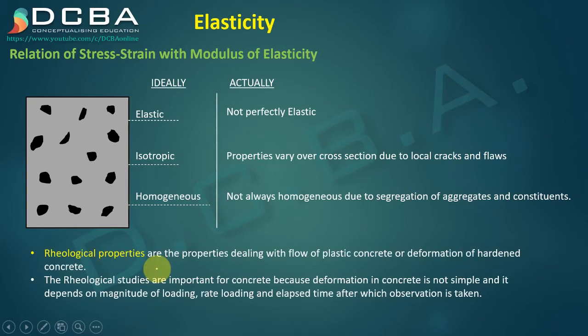So rheological studies are done on concrete, in which we study how the concrete is going to flow in its plastic stage. So it is going to have these two stages, right? Plastic stage, and then it has a hardened stage. In the plastic stage it can flow, and the study of that flow would be called rheological studies. Also in the hardened state, when it deforms due to certain loading, the study of that loading would again be called rheological studies.